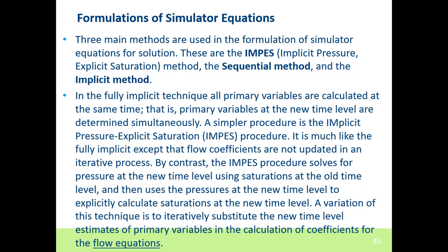You have the implicit pressure, explicit saturation method, which is referred to as the IMPES method, and then we have the 2 major methods, IMPES and the fully implicit method, and the sequential method is somewhere in between.